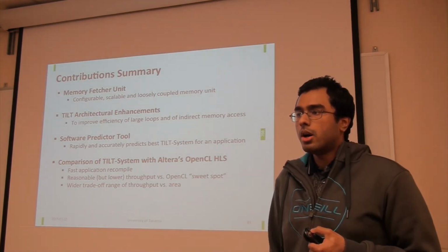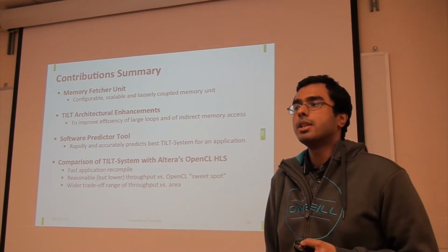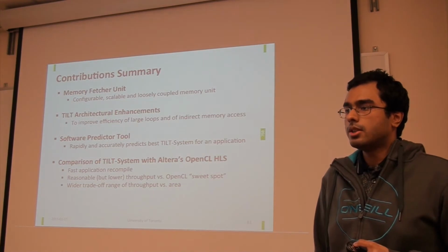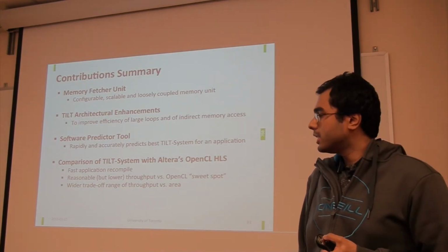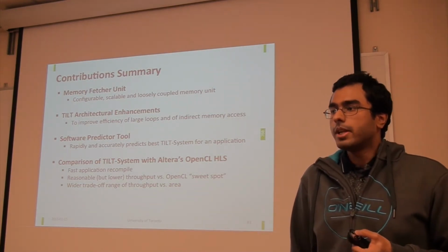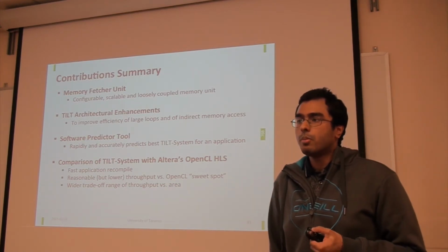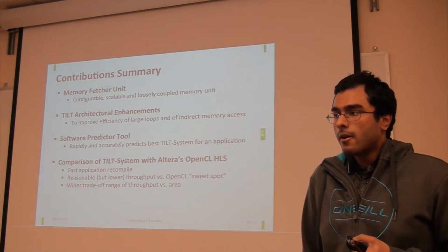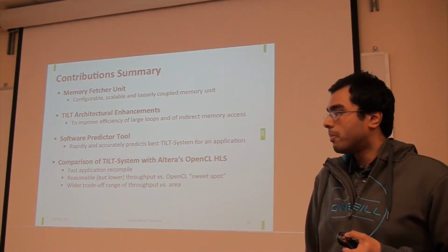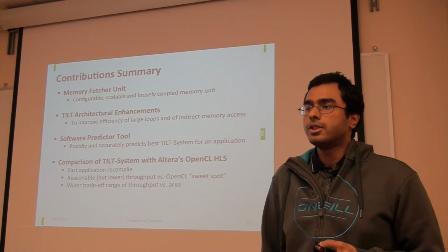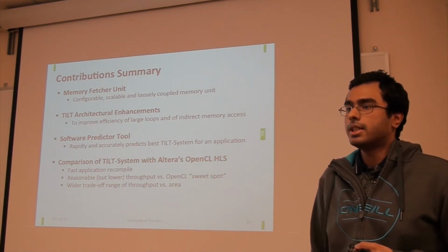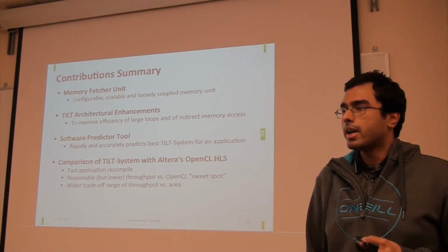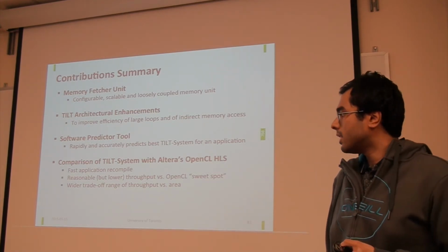Finally, we compare our enhanced and application-tuned tilt system overlay architectures with custom designs produced by Altera's HLS tool. We find that our tilt system has fast application recompile times and also has reasonable but lower throughput versus the sweet spot OpenCL architectures. Further, the tilt system designs present a wider trade-off range of throughput versus area solutions than OpenCL HLS. Therefore, we conclude that the tilt system paradigm is a useful complement to OpenCL HLS.